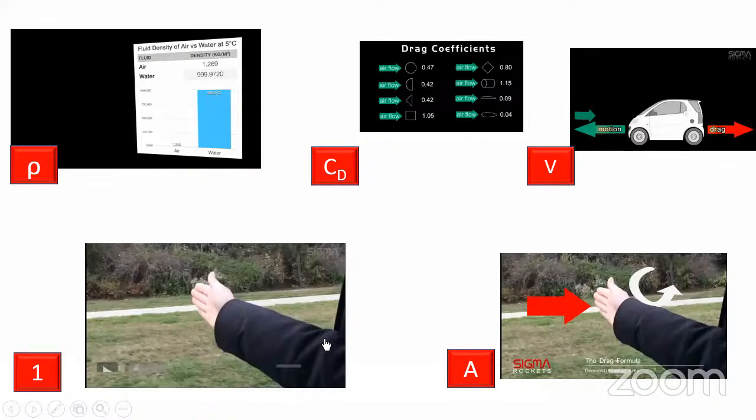No, sir. Normally, if you look at motors, the normal problem with the motor could be that the coil can burn out. There is a possibility, but there is an option for you. You don't have to replace the motor. You can rewind the motor coil.